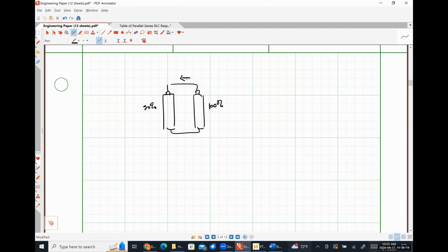Why does it burn if too much current passes through it? That's the answer to all of it. Like an electrical motor, an electrical generator, same thing, just live within your usage. The difference between a synchronous generator and a synchronous motor is literally whether you're using electrical energy to cause the rotor to move, or you're moving the rotor with a mechanical force and generating electricity on the other side. It's literally the exact same machine.